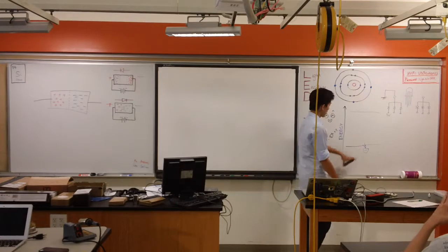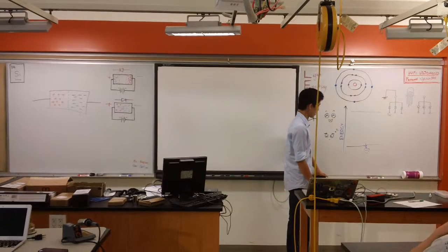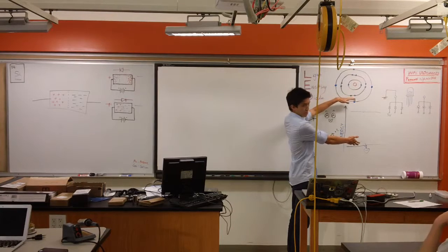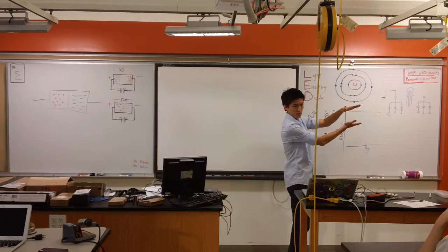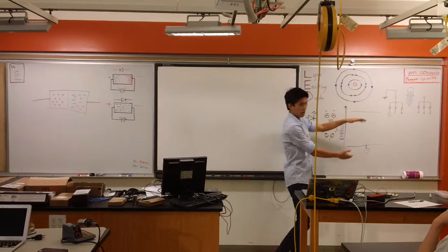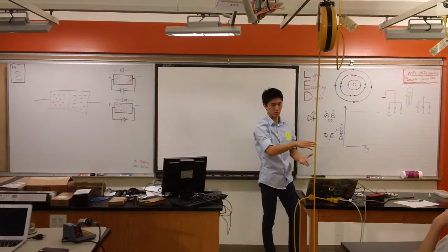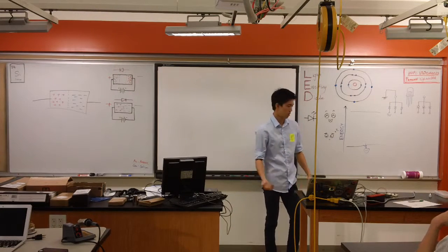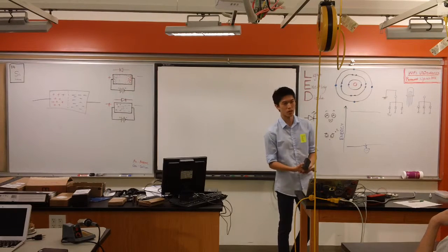So depending on their atomic structure. So this is a silicon, but depending on what you're doping it with, remember how I was talking about the orbitals having specific energy levels? Depending on the material you have, the size of the separation between the energy levels is different. Sometimes you get a really large separation, and sometimes you get a tiny one. And what that corresponds to is the type of energy that's getting thrown out. So that's why we have red LEDs, green LEDs, and blue LEDs.